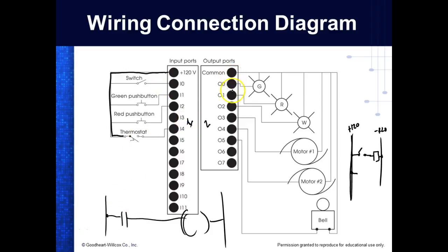Then if I was going to turn on this light, over here I would put what? I would put N, colon. Then I would put the module number, right? No, I just made up something. It looks kind of like a fixed PLC because it doesn't have 16s, but it doesn't make any difference. If it's a fixed PLC, your module address is going to be 0 for both your inputs and outputs.